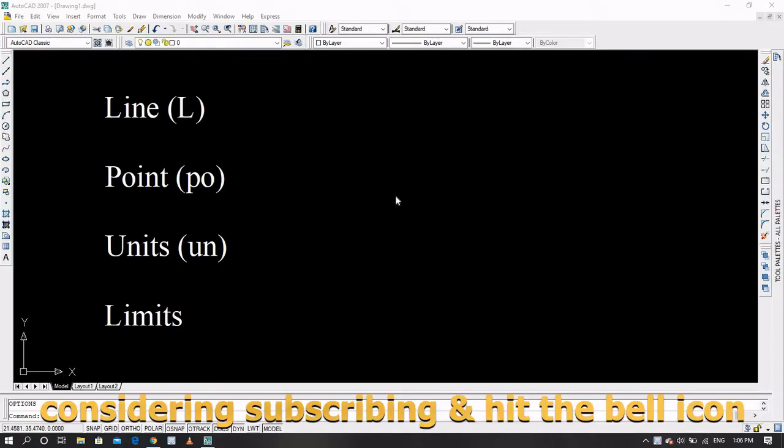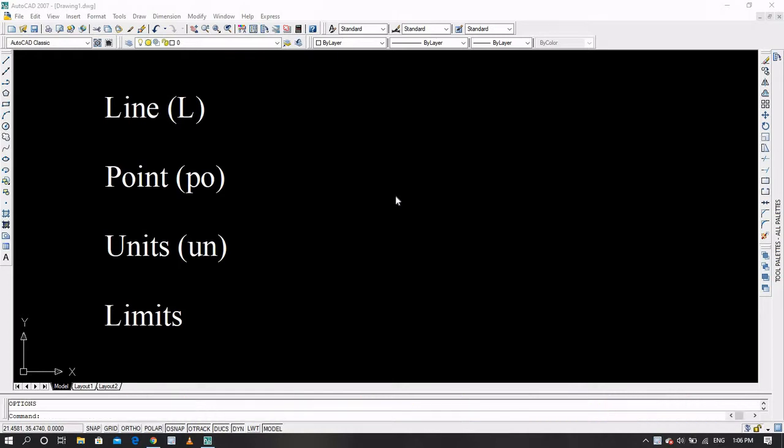In this video, you will learn about line, point, units, and limits. For line, we use the command short key L. For point, PO, and for units, we use UN. And for limits, we will just type limits. Let's start practicing these commands one by one.